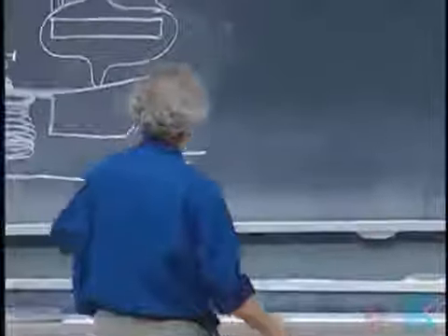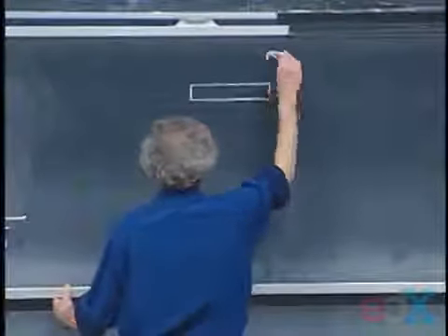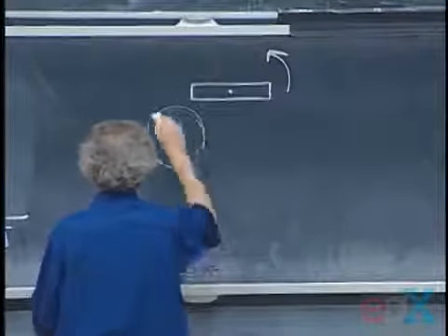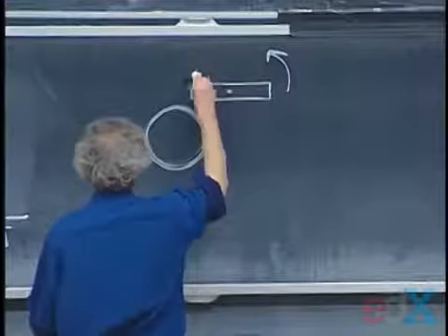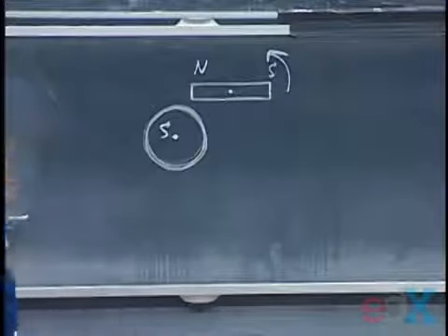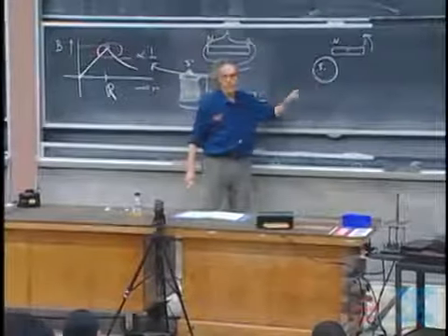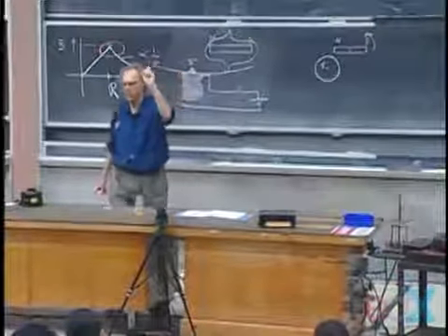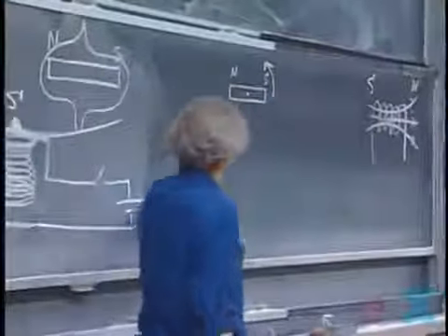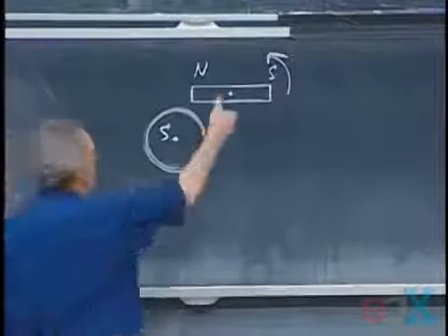I make you look at this from above now. Here is the top seen from above, so it's spinning in this direction. And let's say here is this coil. This is the north pole, and this is the south pole. And I just discussed with you that the current that's going to flow from the battery will make this a south pole. The current can only flow in that coil in one direction. That's just the way it's designed. So whenever the current goes, it's always this becomes a south pole. The north pole is being attracted by the south pole. So notice it's going to be torqued up.